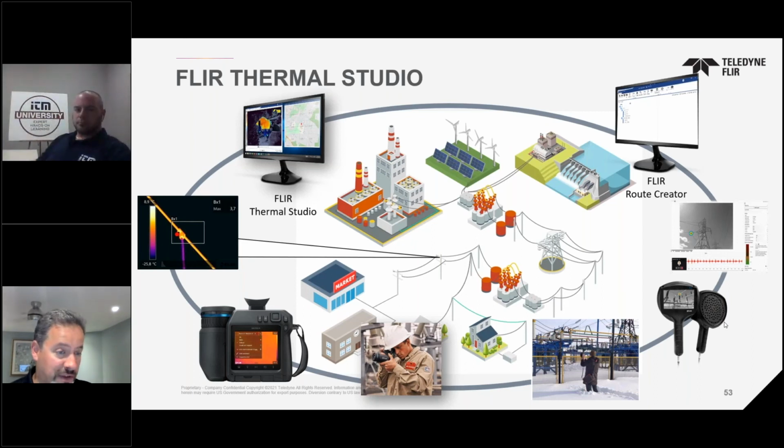Now, I don't know if there's a specific value. Chris, send me that. I can ask our product specialist if we've ever done a study on leak size. I know in our acoustic cameras we don't have that information. In our gas imaging cameras, the optical gas imaging I mentioned before, it depends on the gas. I'll give you an example. For methane and propane leaks, you can get down to 2 parts per million.